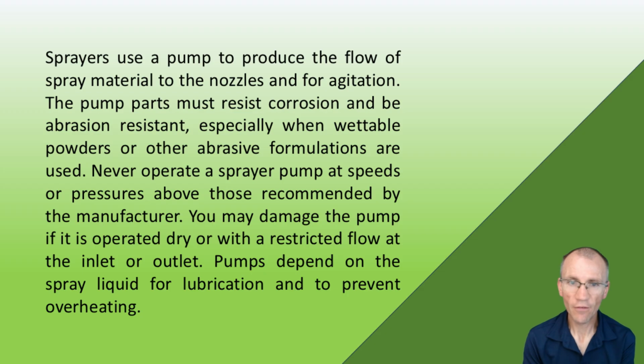The pump parts must resist corrosion and be abrasion resistant, especially when wettable powders or other abrasive formulations are used. Never operate a sprayer pump at speeds or pressures above those recommended by the manufacturer. You may damage the pump if it is operated dry or with a restricted flow at the inlet or outlet. Pumps depend on the spray liquid for lubrication and to prevent overheating.